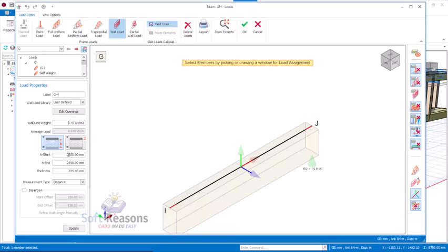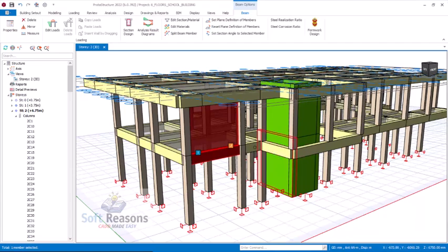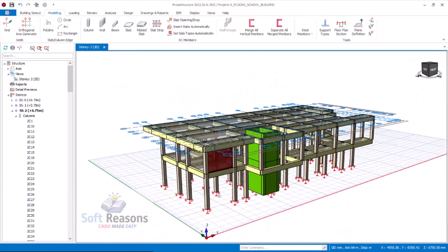You may ask the question, the story height is 3 meters, but if you subtract the beam depth, which is about 500, you should be having 2500. But we'll go by 2550 millimeters here. So you place the wall right there just like this. After which, click on the OK option. So you can now see we have the wall placed successfully.